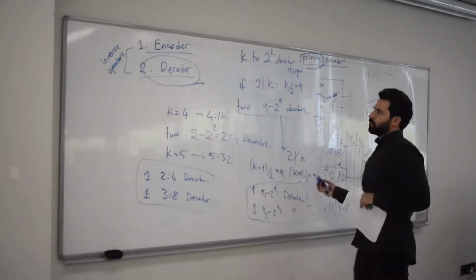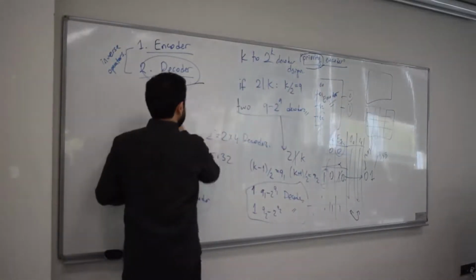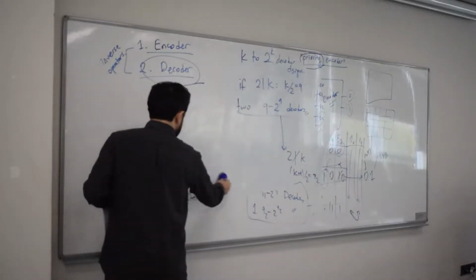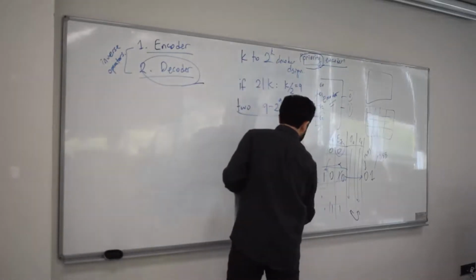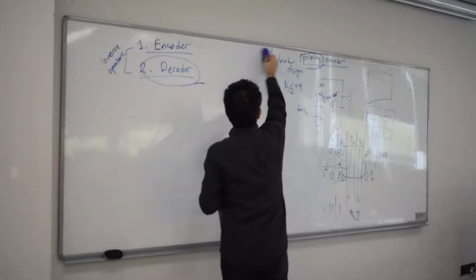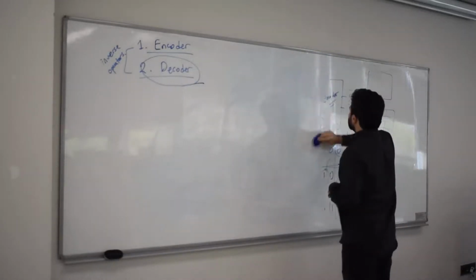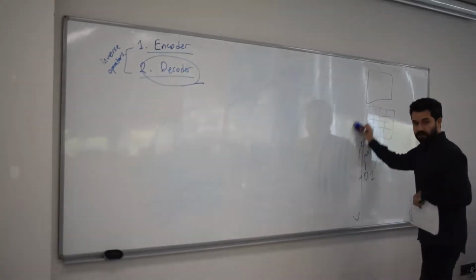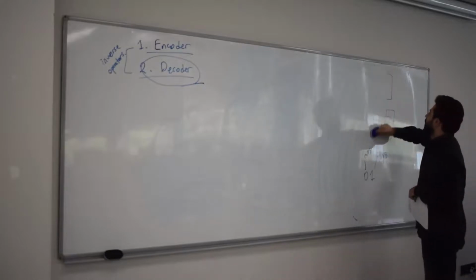Let me continue here. Now, we know encoder and decoder. Decoder is pretty simple. Actually, simpler than encoder, because encoders have this error mitigation problem in the inputs, right? And we talked about that a bit more complicated concept of priority encoder. But there is no such thing in decoders. Decoders are pretty simple to describe, and most of the time we use hierarchical design for both. You can actually apply the same hierarchical design idea to the encoders as well.